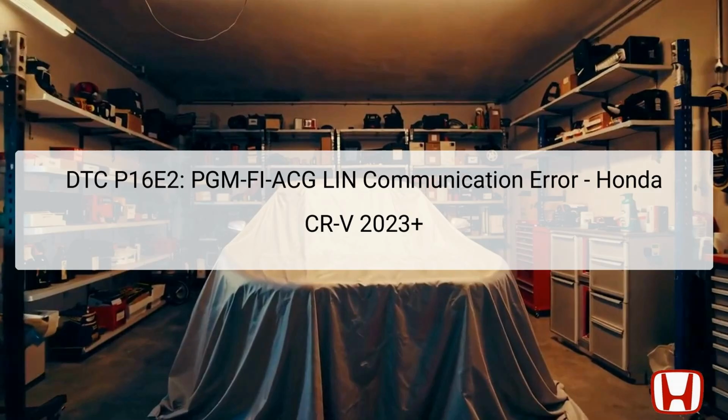If the PCM detects abnormal communication signals, it activates the DTC P16E2, indicating a potential issue within the circuit. The components involved in this error include the alternator, PCM, DC-DC converter, 12-volt battery sensor, and the shutter grille, all of which need to be inspected to diagnose the root cause effectively.